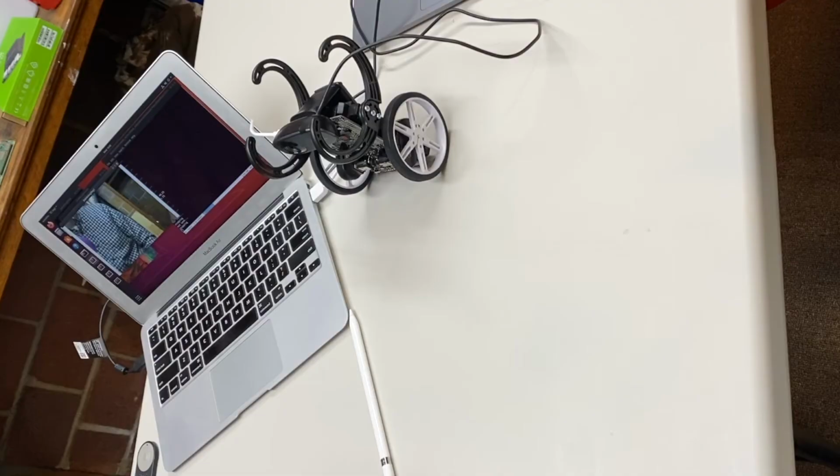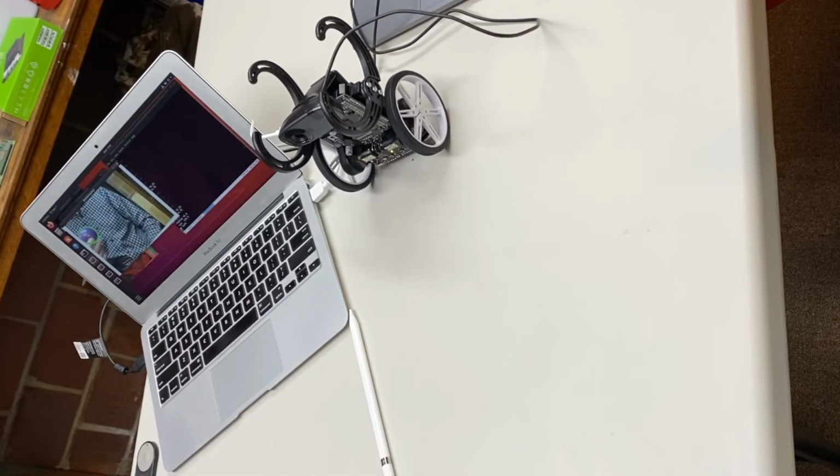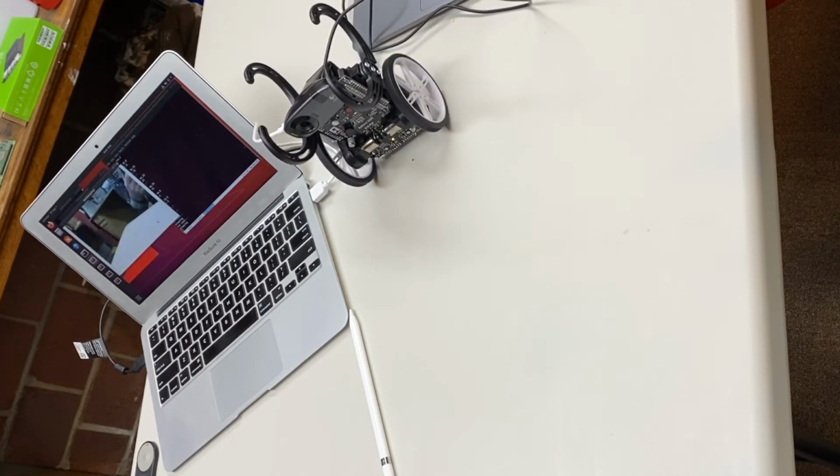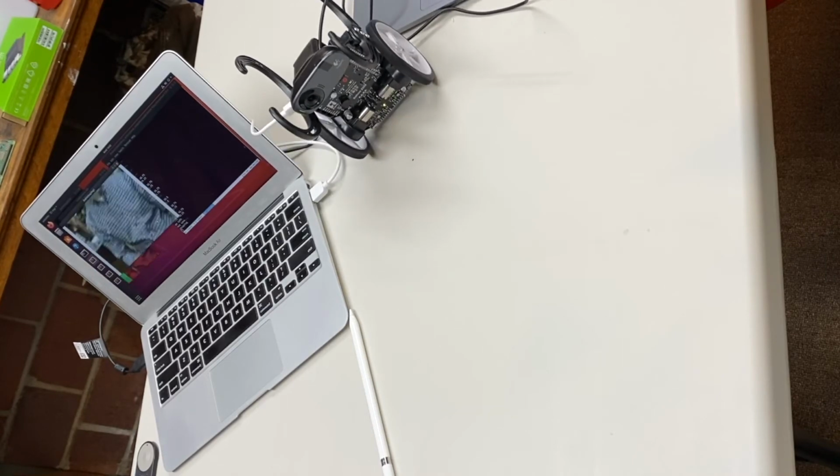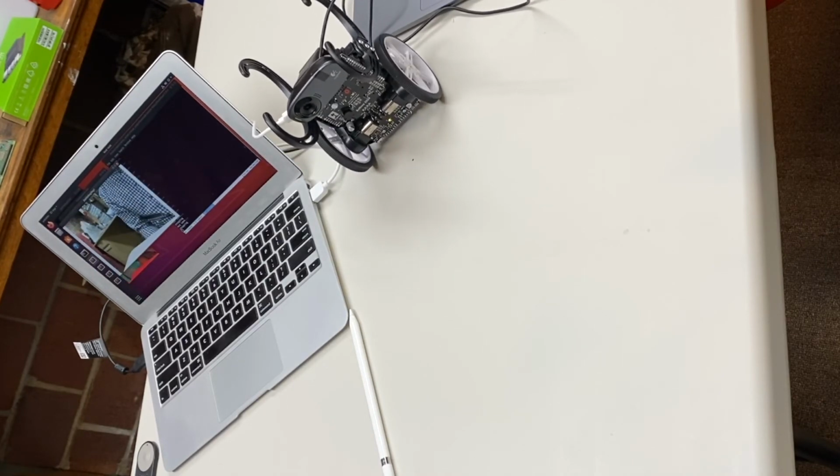One of the things with visual servoing is that you can do this just using a bang bang controller where you're going just left and right based on what you see. You can also do this using a PID controller, or even more advanced types of controllers based on what you want to see. But the fun thing is that it's pretty straightforward given ROS to connect the various nodes together so that you can process image data and output controls for your robot.